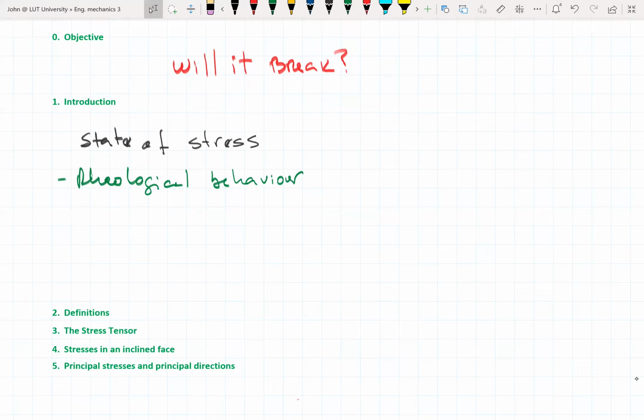For this, one of the important considerations that we're going to be making here, and it is done in many of the textbooks, is that the material doesn't have any discontinuity. It means that the material is continuous in the whole structure of what we're studying there. So if we consider that the material is always continuous, it means that whatever functions we use to describe forces or displacements and deformations are also continuous functions.